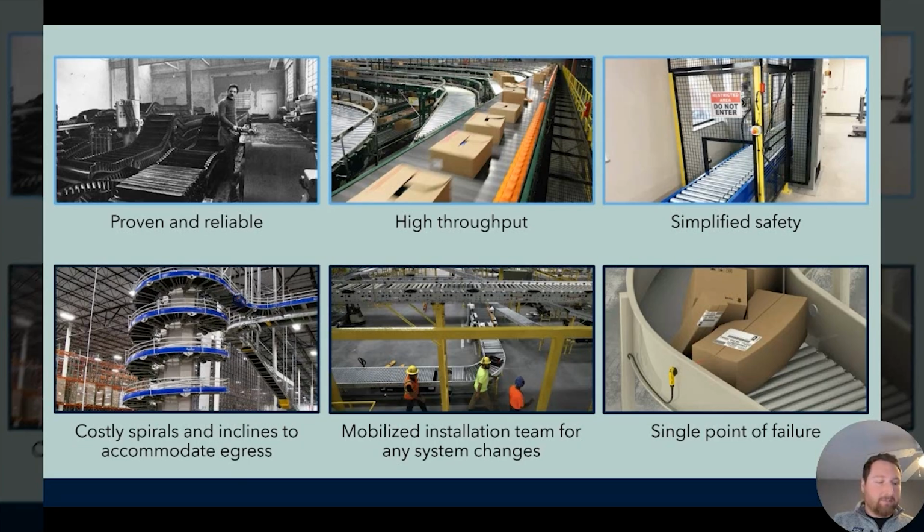As safe as AMRs and AGV systems are, especially in 2025, there is something to be said about safety related to conveyors. That conveyor is going to be in the exact same spot when you come back an hour, a day, or a week later. The same can't be said about an AGV. So you have the ability to have fixed guarding, clear safety areas and requirements that are built on physical infrastructure and not reliant on sensors.